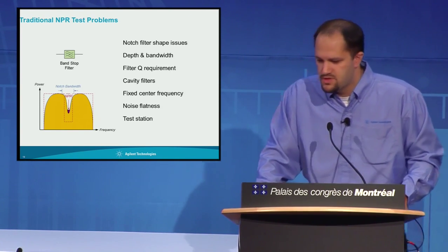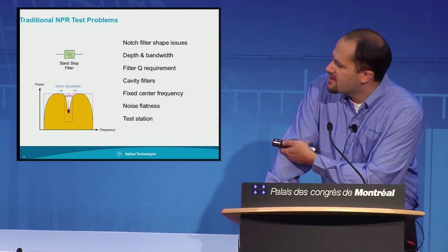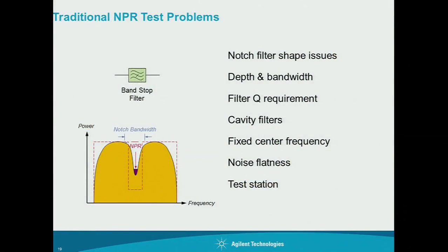The problem you run into is these are typically high Q filters, and again, you still have some rounding issues there. So we're going to talk about some techniques other than the analog approach where you get a wideband noise signal and use a notch filter. Some other techniques can be more effective at creating a nice large depth notch filter.